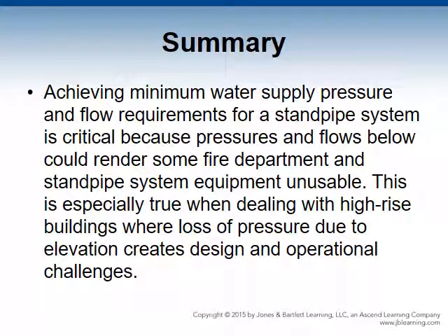Achieving minimum water supply, pressure, and flow requirements for a standpipe system is critical because pressure and flows below these could render some fire department and standpipe system equipment unusable. This is especially true when dealing with high-rise buildings, where loss of pressure due to elevation creates design and operational challenges.